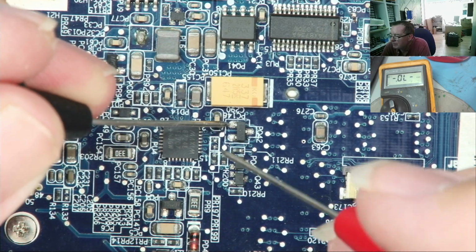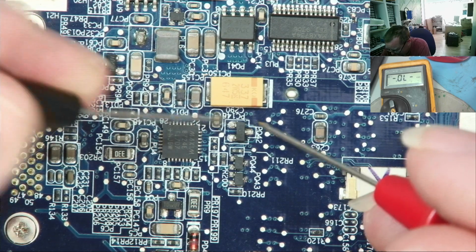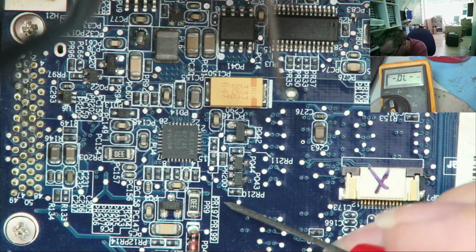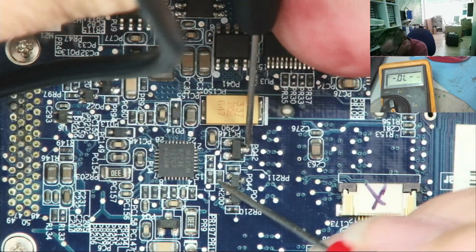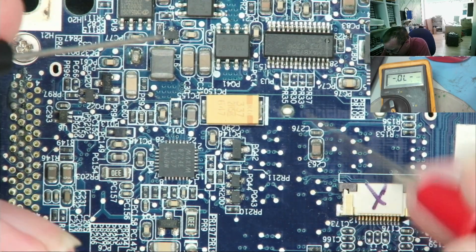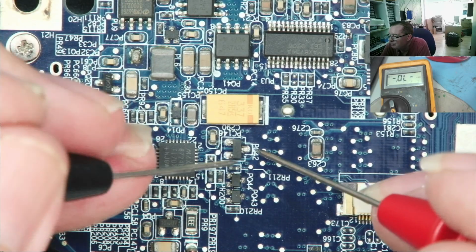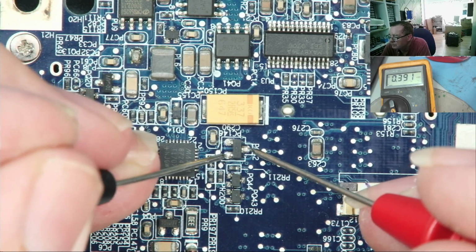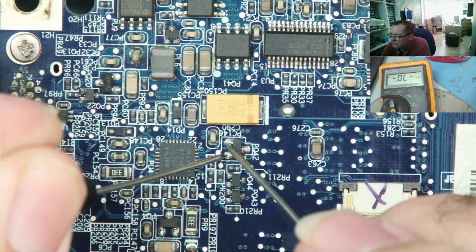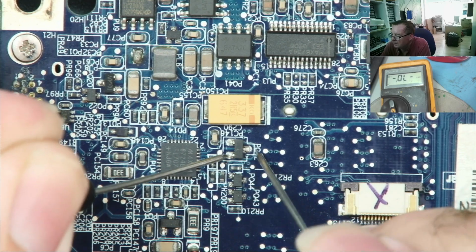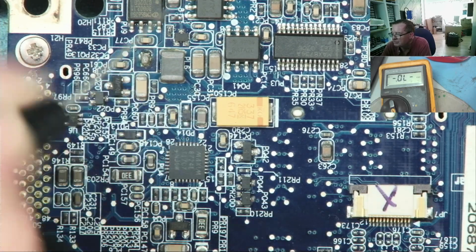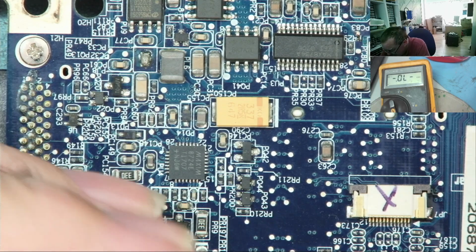If it's a MOSFET, we should see the parasitic diode between the other two. There's a diode junction there. And there isn't one there. So we can say that's a MOSFET. Without the pin out, we can't say if it's N channel or P channel because we need to know which is the drain or source. But we can say it's a MOSFET. Now you'll probably see that we can't switch this on in circuit like I was doing with them out of circuit. And that's because there is a resistance from here to ground that drains the charge. It won't let me charge the gate up. Okay.